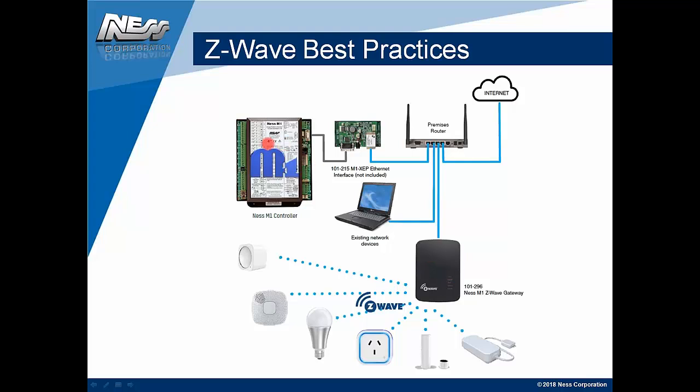So as we update light names, for example, in an M1, and we call it warehouse, showroom, living room, kitchen, whatever you want to call it, as you program in an M1 and get out of program mode, it auto syncs and will bring it into the GUI inside the Z-Wave interface. And then we can program what you want it to do. So when you turn an M1 light on, which of the Z-Wave lights do you want to turn on?